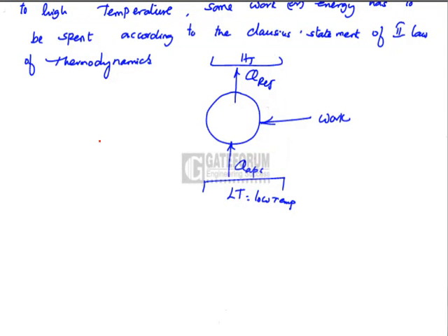First point is, whenever a liquid is changing its phase into vapor, it requires latent heat of vaporization. Same latent heat will be released if the vapor is condensing back to the liquid. Second point is, the saturation pressure increases implies the saturation temperature also would increase. What do you mean by saturation temperature?